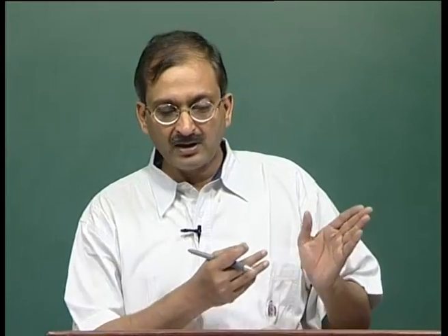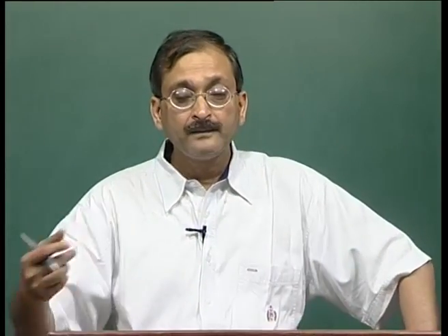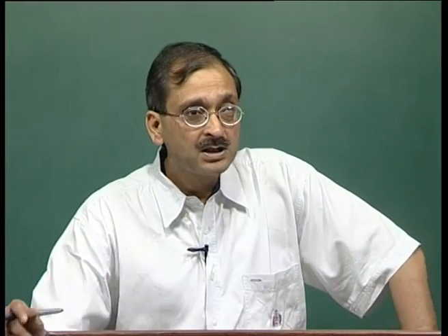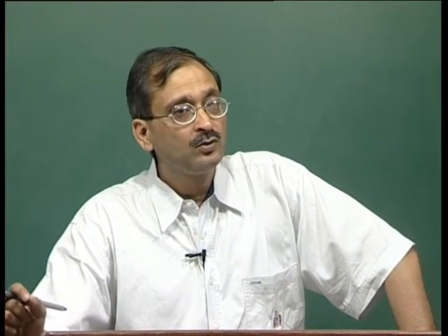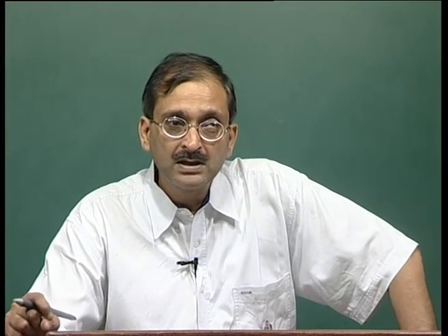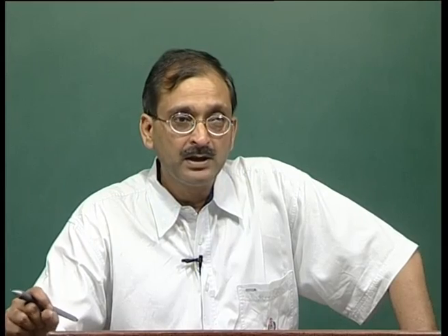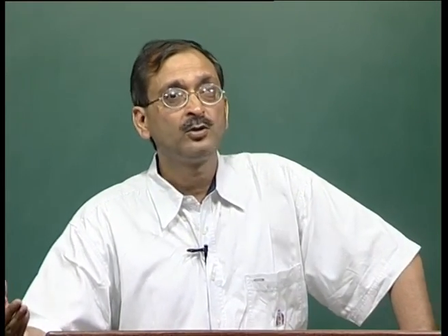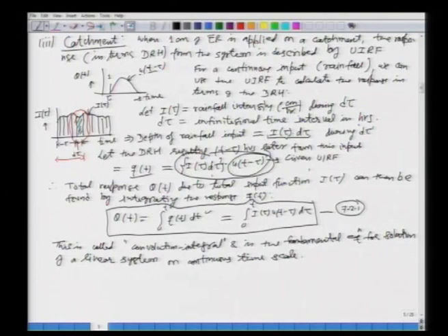So, this whole process of convolution involves lots of processes in the catchment, okay. It may be translation, it may be attenuation, and it may be many other storage effects or characteristics. So, all this convolution process is actually taking care of the transformation of this effective rainfall into the direct runoff hydrograph, all right. That is why it is a very important tool for us. Once we have developed this unit impulse response function, then we can find out the response from any continuous input of rainfall. Okay. All right.